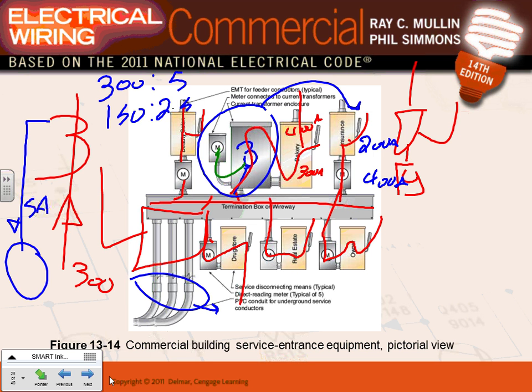So what they do is put meters everywhere for a certain amount of time, and they get the bills from Xcel Energy, and they look at the consumption of power here, and they ask, do they really consume all this energy that's coming out of these conductors? If not, then you can add in, you're done. If they do, then you have to go change what? You have to change the feeders, because you might overload these feeders. Any comments, any questions? Because remember, these feeders are based on what? The load calculation for the building. The load grows, these feeders might have to grow.